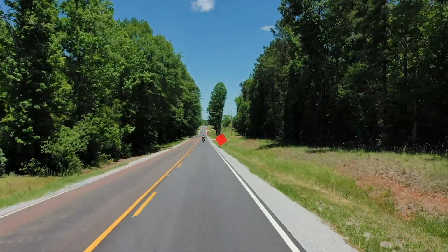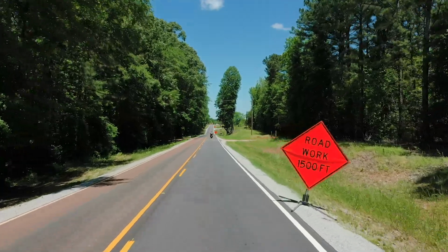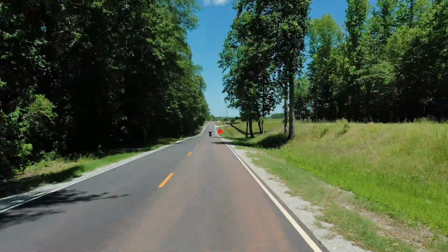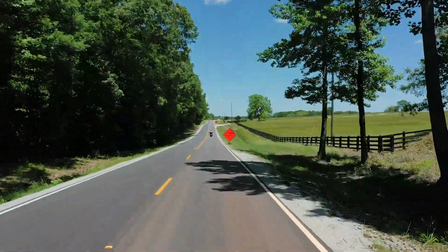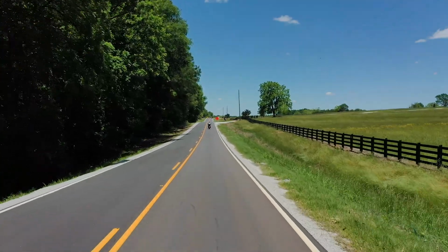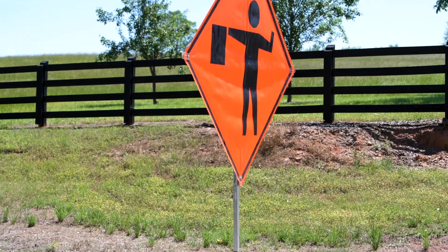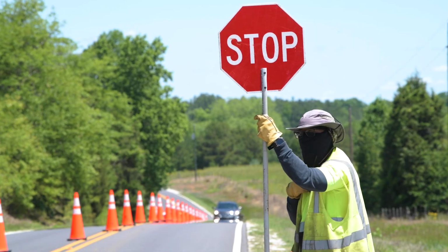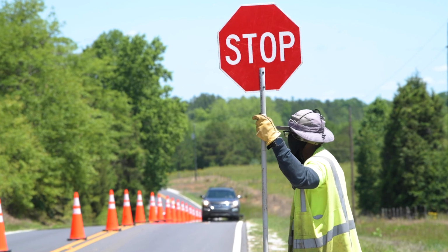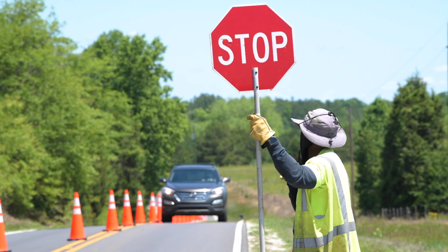As we can see, the advanced warning area begins with the Road Work Ahead sign. This is typically the first notification that road users receive that a work zone is ahead. About 500 feet later, the road users see the 1-lane road ahead sign, and the final sign seen by traffic is the flagger sign. Next, we see the flagger. The flagger is located at the end of the advanced warning area. The flagger station has been placed for adequate sight distance for both the flagger and the road users.